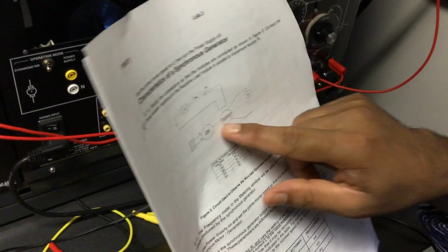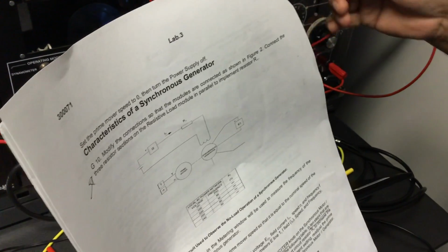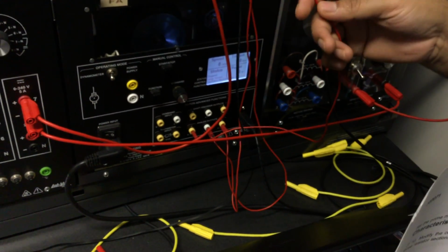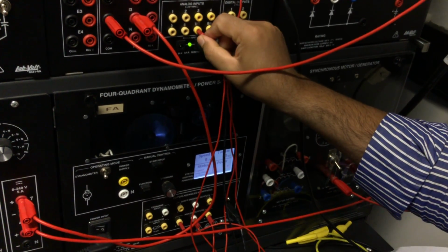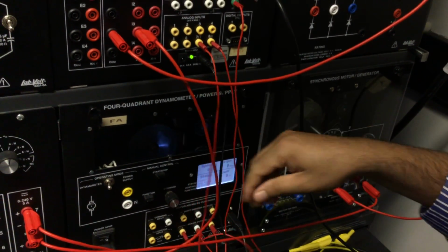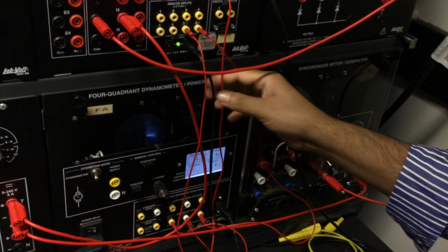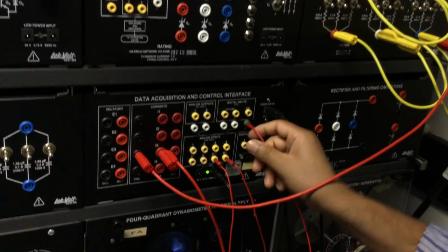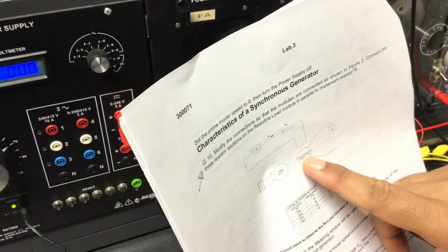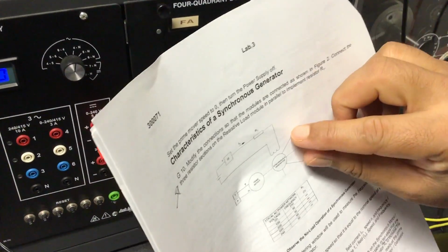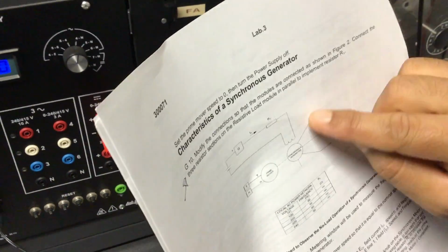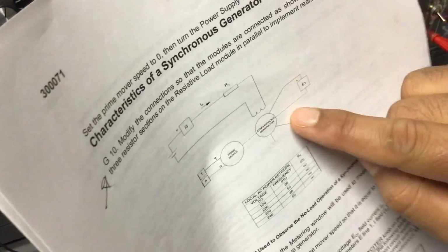As for the armature side, it's the same thing. We already connected it previously. This is the speed. The output of speed and torque is connected with the data acquisition system. We also connect the grounding, same as previously. This time for the synchronous motor, we need to connect the voltmeter between 1 and 2. There are 2 lines for 3 phase, line 1 and line 2.